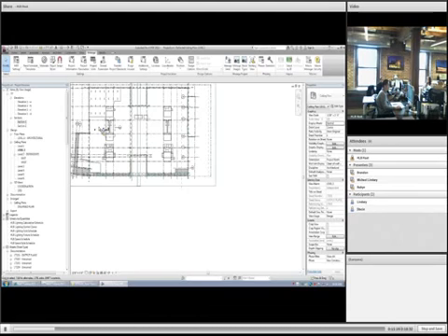You have to then go to section view and then put it in place. Yeah, that's for your HLB fixtures because they are completely manual. The numerical controls for changing elevation are only so good. It really demands a user going in and changing them. But also, when we linked in the Revit file, they didn't quite align up. We aligned them in plan, but then obviously not in the other 3D.